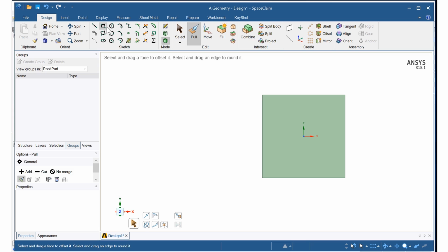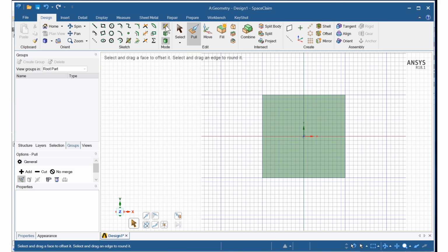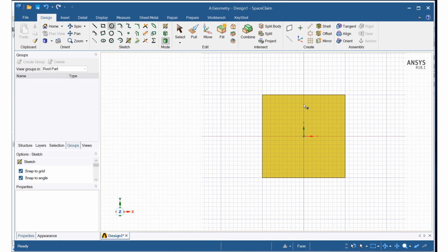Now I'm going to create my circles, but I need to go back to my sketch plane, so I click this top there. Now I click on my circles, and you can see that right here with the cursor the way I have it, I will not be able to draw a circle. I need to have the pluses checked. So I click once, now I have my plus, and I can go ahead and generate my circle. I'll make these circles 4 millimeters in diameter.